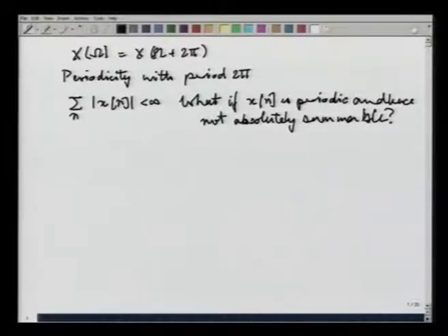This is reminiscent of the similar situation that we faced in the context of the continuous time Fourier transform, which was originally meant for finite energy signals, but which got extended to the case of finite power signals as well to give a unified formulation at a later stage. Let us see if we can repeat that performance over here, and the way we do that is to guess that Dirac impulses must have something to do with it. Suppose we place a Dirac impulse, or rather as is really required in the case of the DTFT, a train of Dirac impulses placed 2 pi apart from each other on the omega axis, and see what its inverse transform will be.